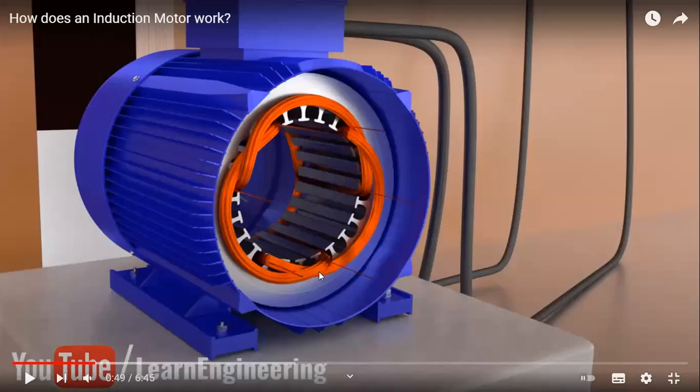This is the steel material. We also mix this steel material with other things like silicon, so that it has high permeability. Also in the DC motor, you can clearly see the slots of the rotor are highly permeable. We make it highly permeable so that the flux can go through a low reluctance path. Low reluctance means a low resistance path.